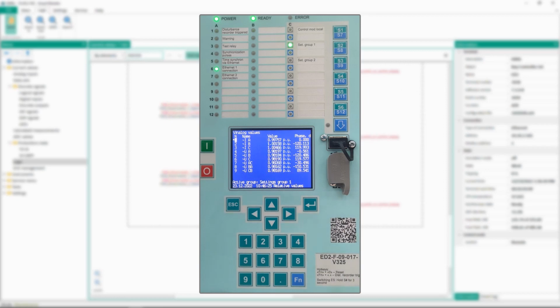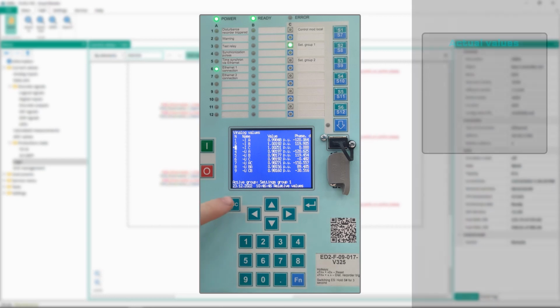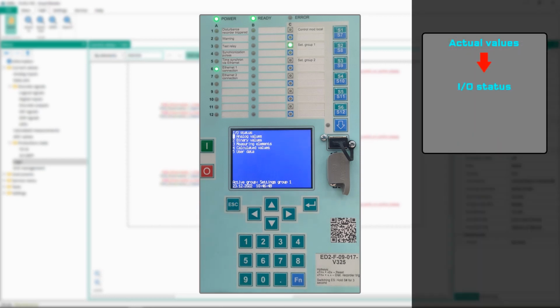The basic signal, relative to which the value of the phase angle of remaining variables will be calculated, is selected by pressing the Enter key on the required analog signal. After that, a mark in the form of a star will appear in front of the sequence number of the selected basic signal.